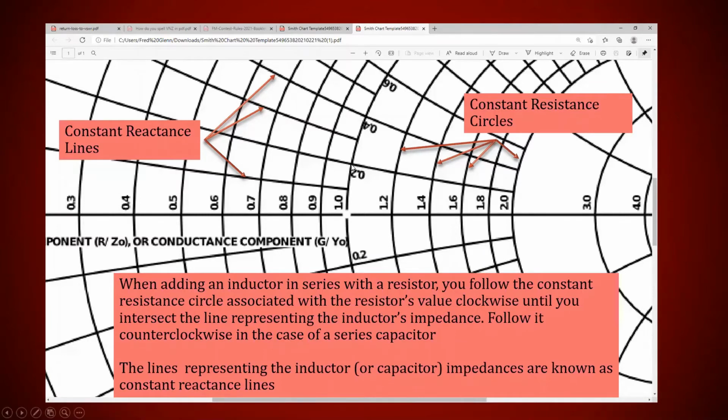And this is basically just a scale, the same way the other graph was. And it's an impedance plot. And the people who teach Smith charts will say, oh, it's not an impedance plot. It's actually a plot of the infinite gamma curve, gamma space. Well, remember, gamma is the reflection coefficient. Gamma is resistance and inductance. It's impedance. It's all of the same stuff. So don't buy into that. It's an impedance plot is the way to take a look at it. It's the easy way to consider it.